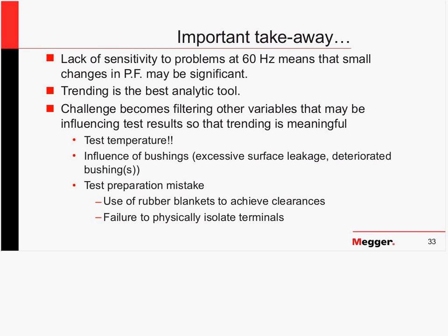A huge variable in power factor testing is test temperature. If you are not correctly compensating for the temperature at which you're performing the power factor measurement, then trying to do trending and detect small changes in power factor becomes almost unrealistic. There are other variables listed here too that could influence your test results in a non-representative way. At the end of the day, you want a representative power factor.